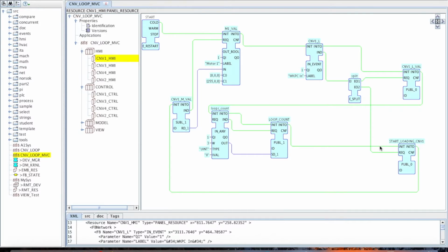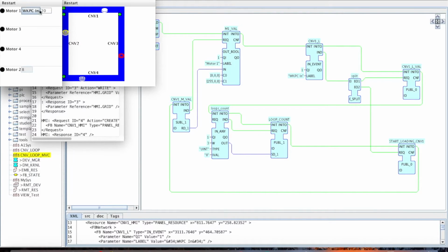But then also we need to provide a signal to the controller that we have inserted a workpiece. So this button, what we have in our UI, can be seen as a button on some operator panel. For example, when the operator puts a workpiece in the beginning in this trivial system and presses that button on the pallet, the controller receives a signal thanks to this start loading scene v1 block and starts its operation.